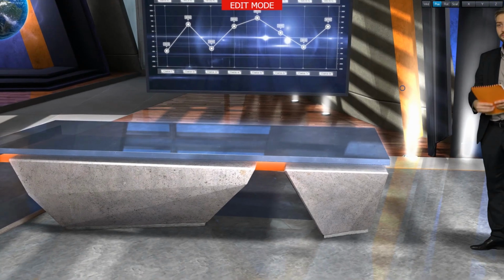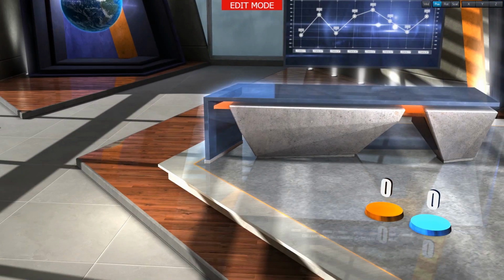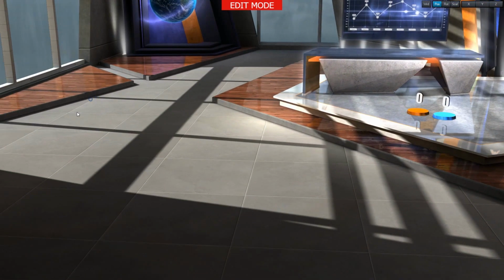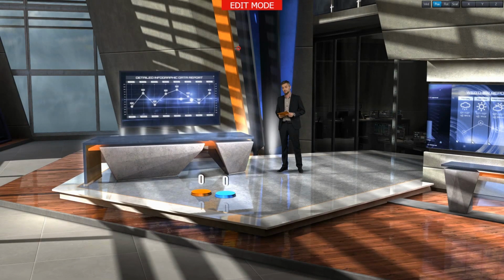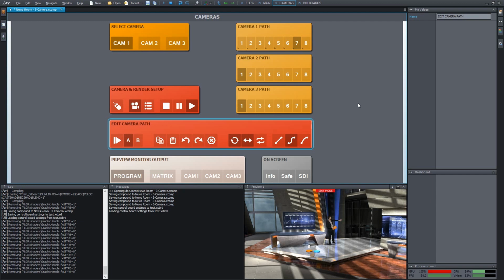Now let's set an initial point of the new camera path. A distant view like this, for instance. Now let's set the end position of the path. The most convenient way is to set the endpoint, starting from our starting A position. It is quite easy to achieve this. While we have marked the A point, we click on the copy icon, then we select the B point and click on the paste icon. We have now overridden the old B position with this new one.